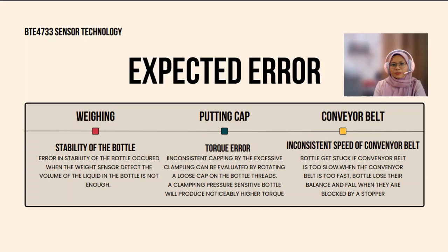By adjusting the speed so that it is neither too fast nor too sluggish, the controller positioned behind the transfer cover panel ensures that the speed is optimal when the water bottling system is running. When the transfer cover lifts up, the limit switch will be open and will trigger the alarm.